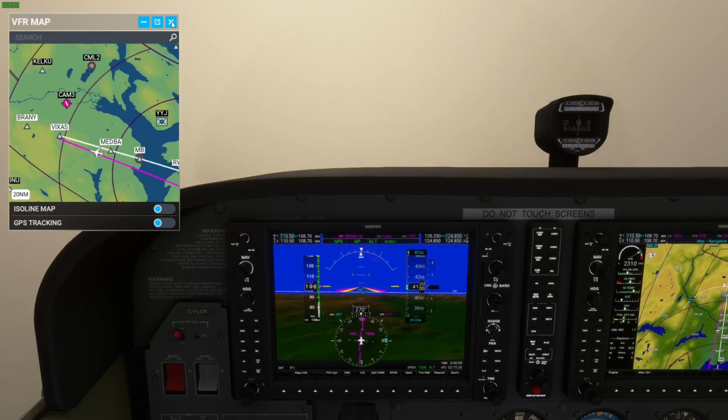What we're using the 172 for is to show how, once GPS was approved for navigational landing and for landing an aircraft, it integrates with the old-fashioned precision instrument approach procedure. Now, the indicator here in purple means that the navigation is set for GPS approach, which we call RNAV. It's one form of RNAV where you're using radio navigation to approach.